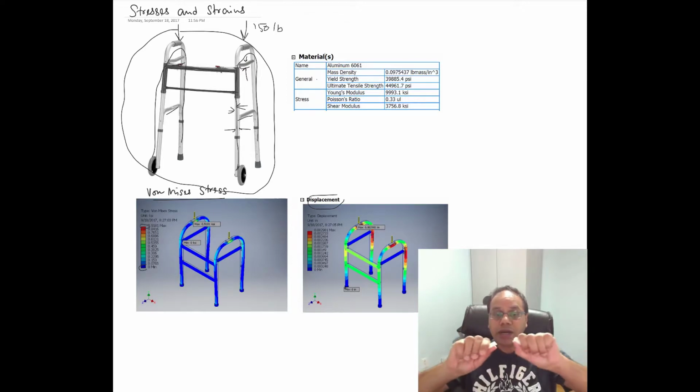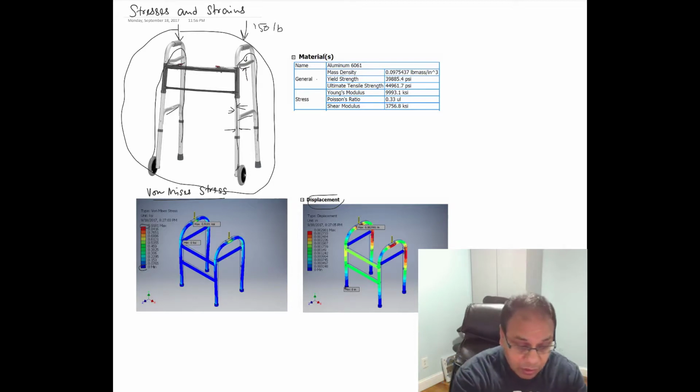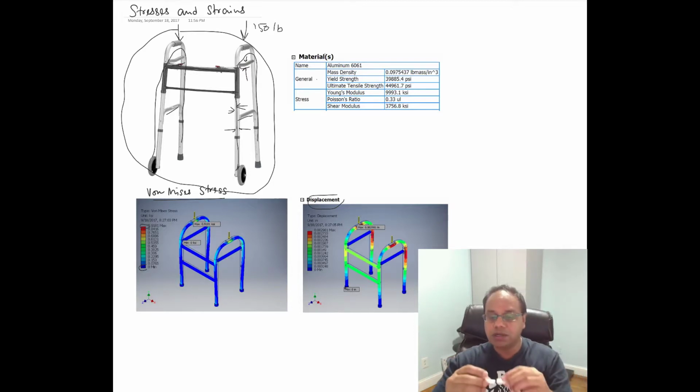So I'm going to apply a bending at 2 ends, and you see in this case also we get almost like a flat cross section. So it's almost like the tensile load that we applied. Now the same load on a ductile material will give a different kind of cross section. So I already told you that on a ductile material, if you apply the tension, you'll have a cup and cone kind of structure. Okay, if you apply torsion, you will actually get a different kind of structure. In fact, for a ductile material, it will be almost like a flat surface.